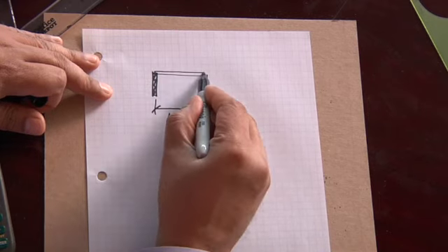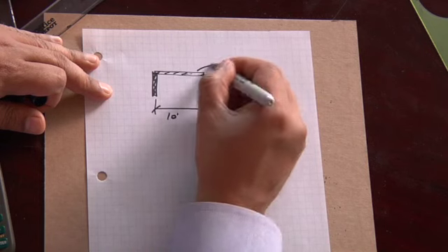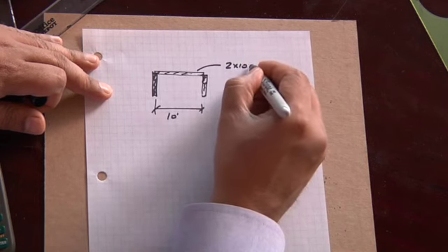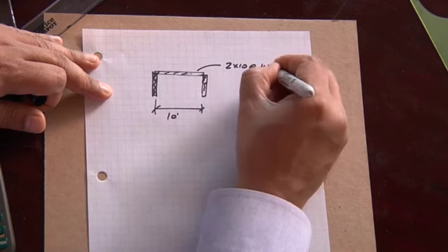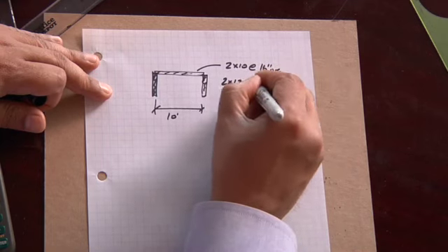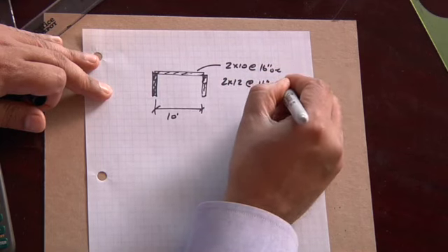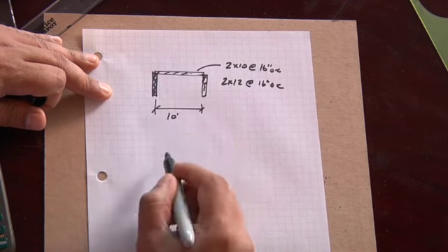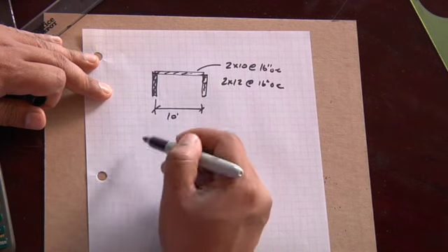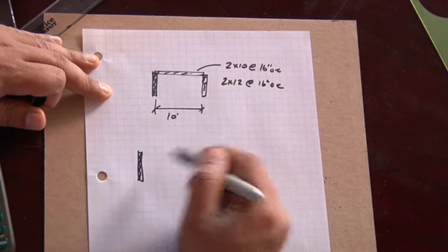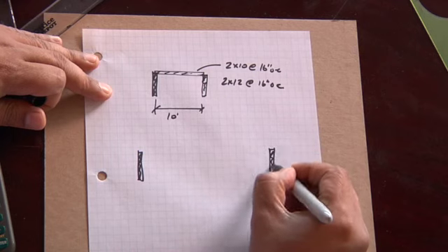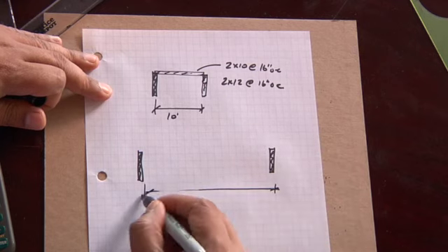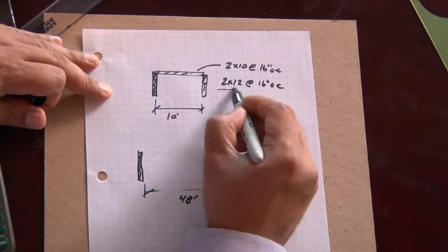the joists are going to be fairly reasonably sized. They could probably be a 2 by 10 at 16 inches on center, maybe a 2 by 12 at 16 inches on center, depending on what the deflection requirement is. But if you lay out a floor plan where your bearing walls are 48 feet, clearly you're not going to be able to do that with 2 by 12s.